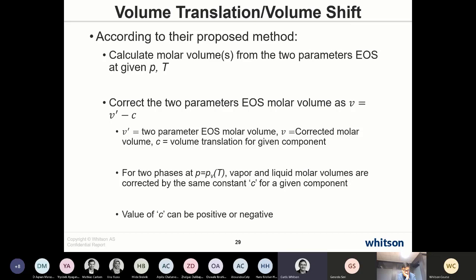And those correction terms were highly nonlinear. They were using spline tables. They were difficult to reproduce. They basically introduced a lot of complexity in order to get both accurate gas and oil densities. And in reality, with these correction tables, the pure component critical properties were not being honored: Tc and Pc, acentric factor.